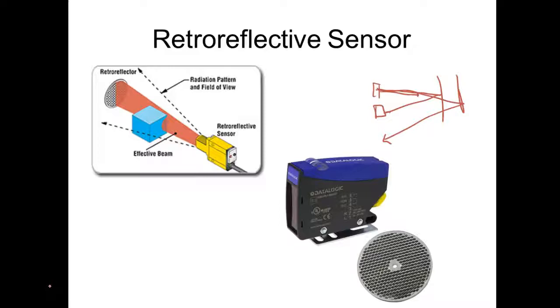But we're going to run these into a digital device. So what does that mean? Well, that means these guys have got electronic circuits in there, so they're going to have to be powered. It's got a single bit analog to digital converter inside of them, but it gives us the ability to set the sensitivity.